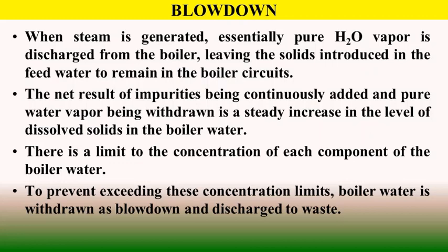Therefore intermittently the blowdown is allowed to maintain the concentration to a level within the boiler water steam circuit for the particular boiler design and pressure. When this concentration level is reached, the blowdown valve is opened for a short period of time to reduce the concentration of impurities, and the boiler is then allowed to reconcentrate until the control limits are again reached.